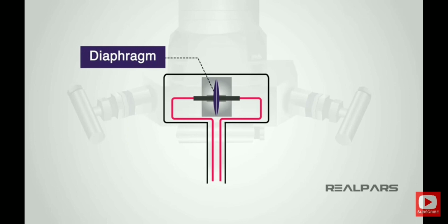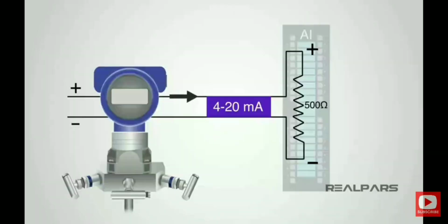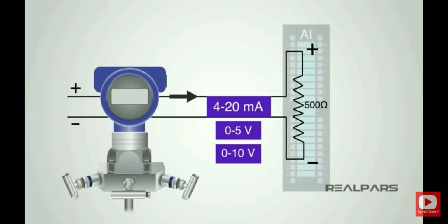Sensors such as differential capacitance, vibrating wires, or a strain gauge are used to produce electrical signals that will be sent to the electronic housing, where they are processed, converted, and amplified into a current or voltage signal output. They can be read by the control system. The electrical output generated by the DP transmitter electrical module is linear and proportional to the actual measured delta P.